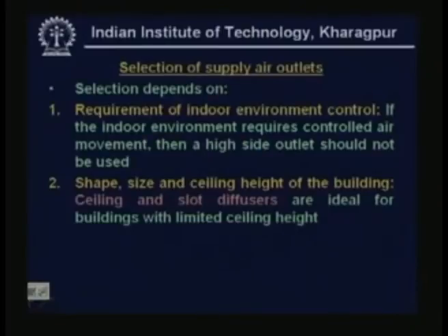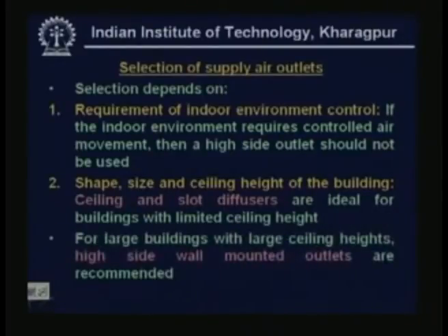And it also depends upon the shape, size and ceiling height of the building. Ceiling and slot diffusers are ideal for buildings with limited ceiling height. For large buildings with large ceiling heights, high side wall mounted outlets are recommended. Okay.